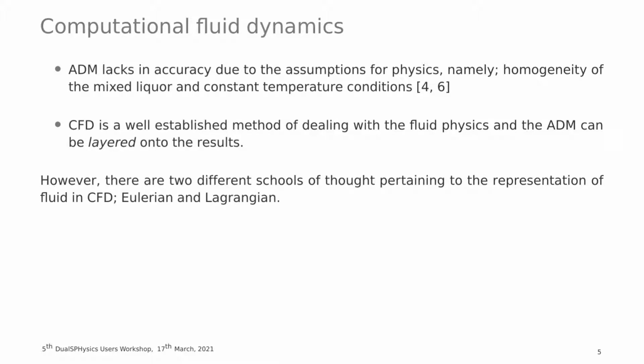ADM is quite nice, but what it lacks is that it makes certain assumptions. First is the homogeneity of the mixed liquor, or the homogeneity of the sludge, which is never the case. And second is constant temperature conditions. So the tank itself is temperature controlled, but there is never constant temperature. CFD, on the other hand, is well established to deal with these problems, and what we aim to do is layer these ADM results onto these CFD results.